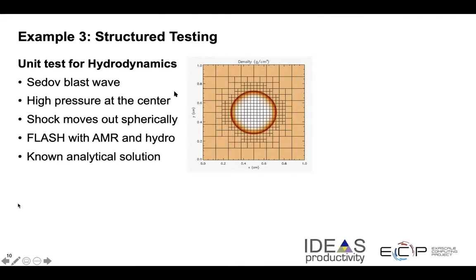Here I'm showing a test of the Sedov blast wave, which is simulated using the grid cell fills and equation of state that are previously tested. The Sedov wave has a known analytical solution which provides an error estimate of the implementation. And out of tolerance errors at this stage indicate a problem specific to the hydrodynamics, that is the movement of stuff between the cells, because we've already tested the other pieces, since the cells and equation of state are already tested. In addition, plotting errors versus space and time helps to train graduate students.